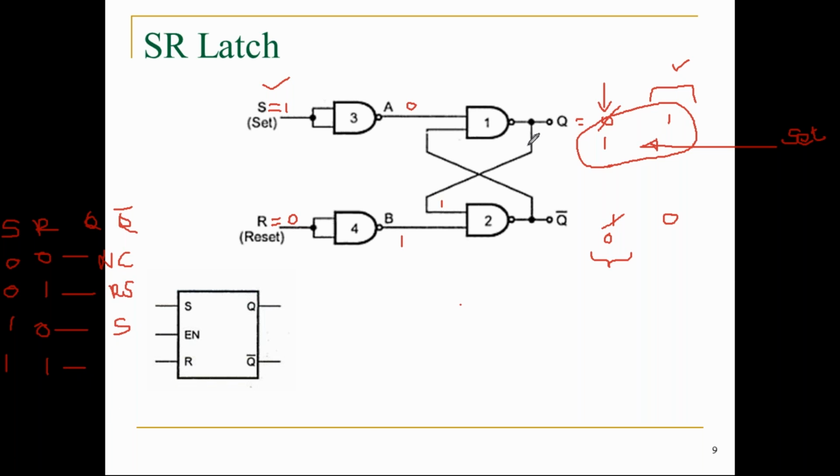Now we are entering into this. Now the assumption is 1 1. Okay, please listen. It is another one thing you should keep in your mind. Both inputs are 1 1, that means S input equal to 1, R input equal to 1. Since there is an inverter, here 0 and 0. Then one input of both AND gates is 0, which means 1 and 1 at the outputs. So it is not possible. Please listen, both 1 1 is not possible.